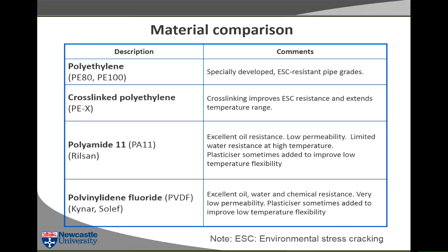So the polythene that's used in liners is sometimes cross-linked, just very, very slightly. It means you can't subsequently remelt the material and use it for something else. But it improves its temperature resistance by about 20 degrees C. So that's called PEX. If anybody mentions PEX, that's what PEX is.